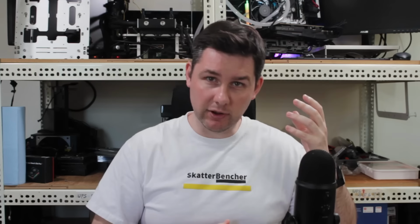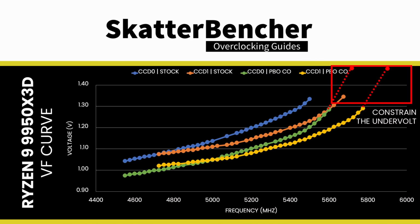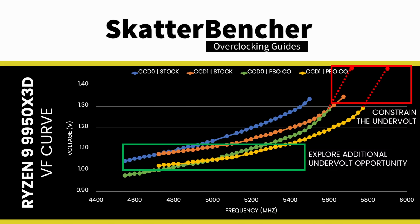The idea of Curve Shaper is that you can tune specific parts of your VF curve. For example, you could say that you only want to undervolt in the high frequency range at high temperatures. For example, if you want to tune for an all-core workload. In our case, we want to use Curve Shaper for 2 reasons. First, we want to constrain the undervolt in the peak frequency region to stabilize the Fmax plus 200 setting. And 2, we want to explore additional undervolting opportunities for all core workloads. For the first objective, we can use Curve Shaper values for high and maximum frequency regions. For the second objective, we can use negative Curve Shaper values for low and medium frequency region.